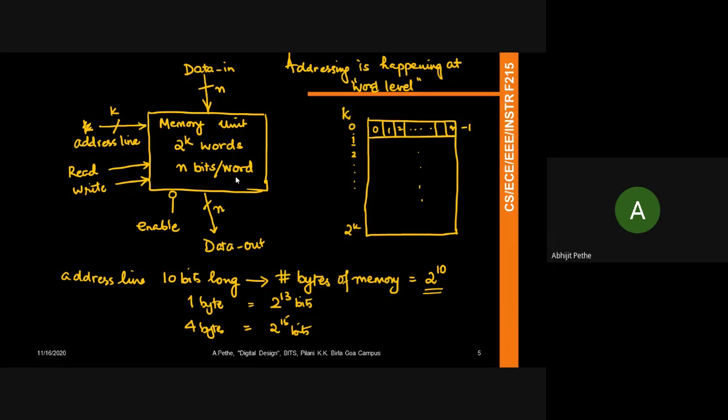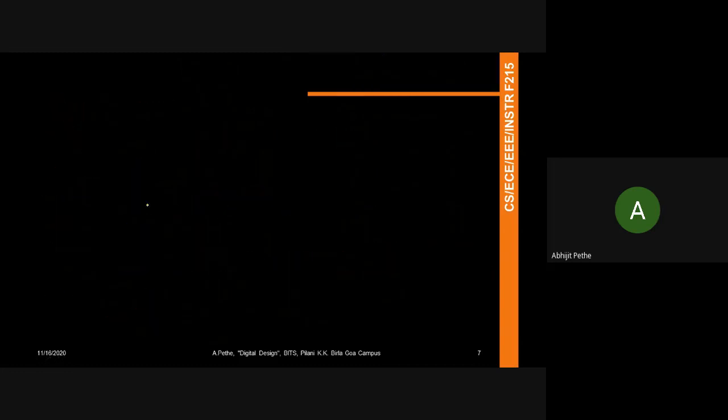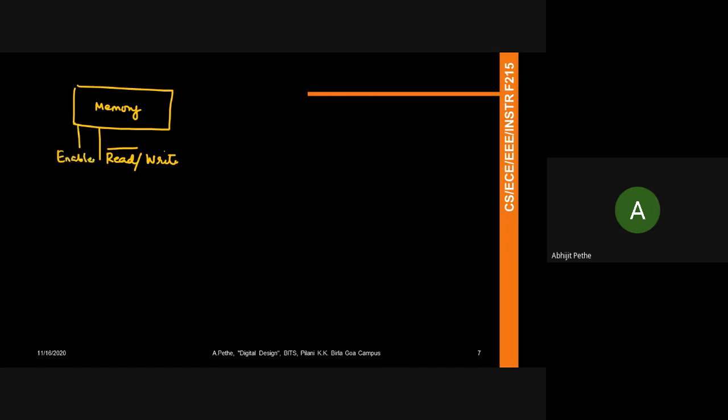So as I suggested, one way to think about these signals, the other way would be that you can also think of this as one enable signal. So suppose I think of my memory. Suppose I think of a signal read comma write or read slash write, right? And I can call this read bar slash write, and I'll talk about another signal, say an enable signal. So I can also design access memory like that. I can say, let's call this signal enable. Let's call this read write signal. I mean, by doing this, I've already given you the logic, right?